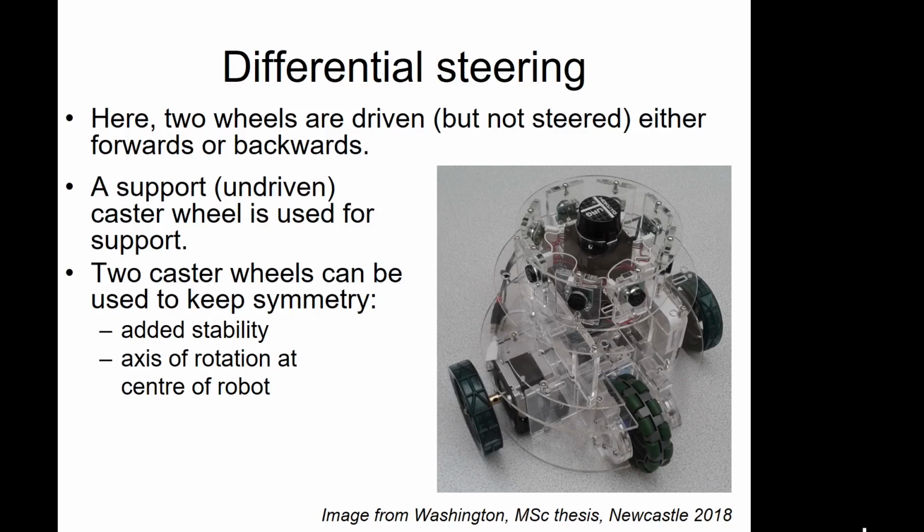So what we'll do is just look at some typical geometries of how we'd build a robot up to get us started. The simplest kind is called the differential drive robot. Here you've got two drive wheels, so these are your standard wheels. This is a student project, and the student built a robot consisting of two drive wheels.